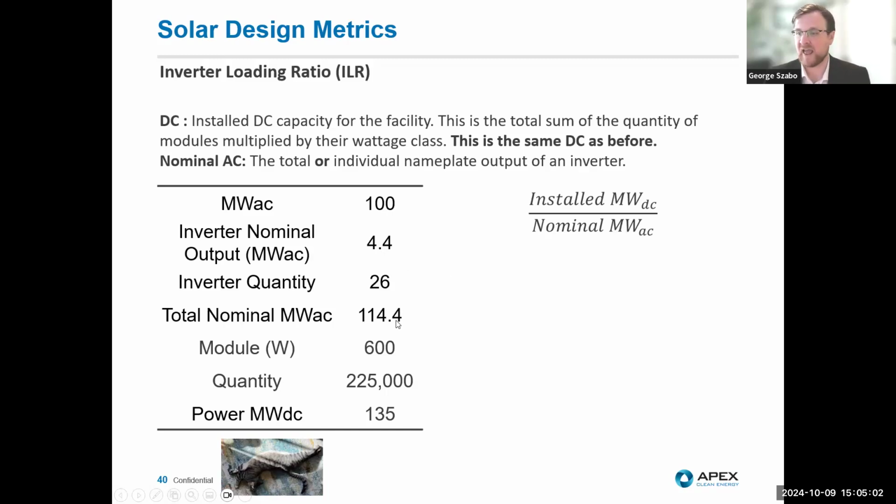So why would we want to have more nominal or nameplate power from the inverters? Well, there are reactive power requirements at a solar facility. The majority, if not all, of utility scale solar farms are required to be capable of supporting plus or minus 0.95 lead or lag power factor.